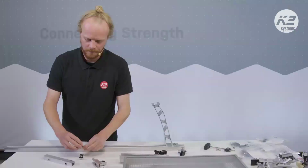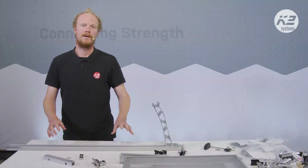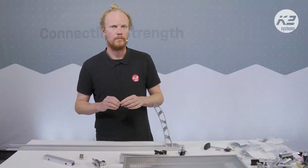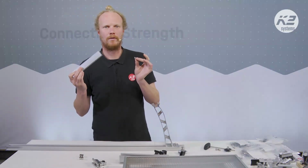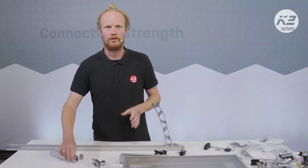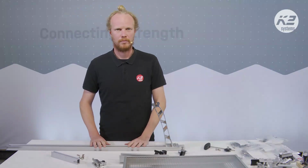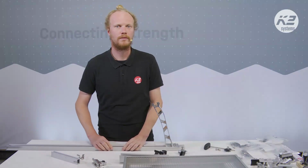So for the flat roof systems, if we do have an Express system and you want to make sure that the whole rail is at the same potential, these are required for our rail connector sets. If you are going to be doing, or are really concerned about, the electrical equipotential bonding and the lightning protection side of things, we would recommend the continuous rail system.